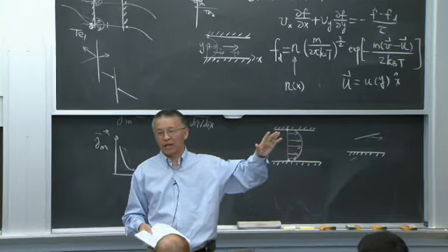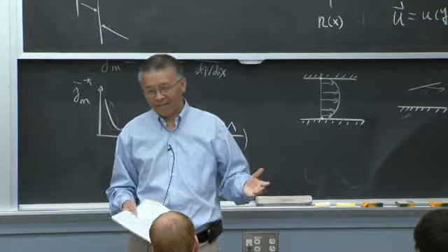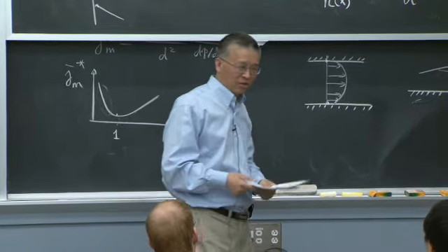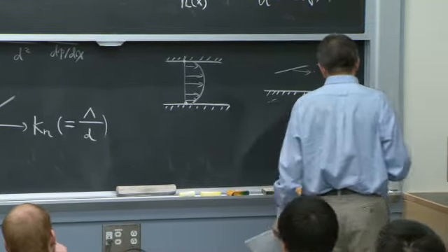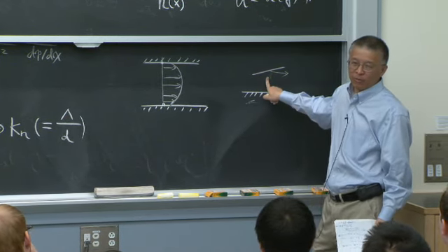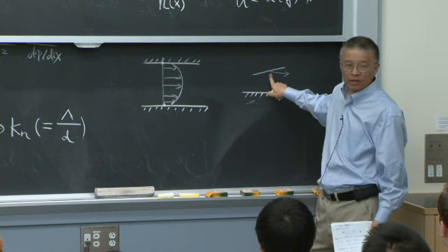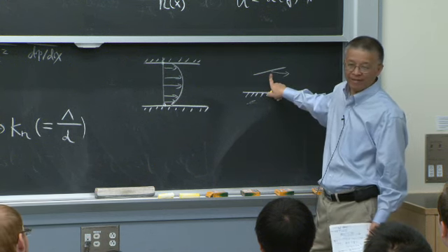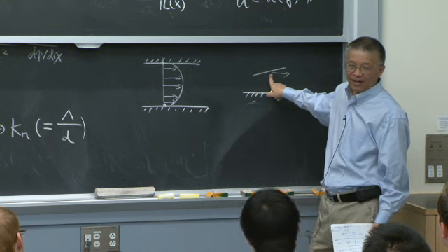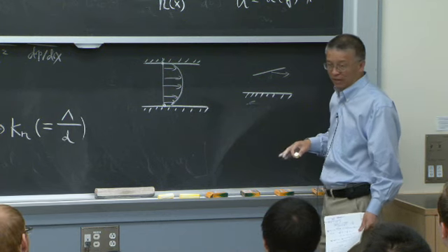And now this fly height, I'm mentioning to you, is about 1.5 nanometer. Okay, that's why it's such an important problem. We never found out the reason. I mean, it could be the molecules, it could be adsorbed molecules, it could be the finite size of molecules, right? But it's a very relevant technology problem.